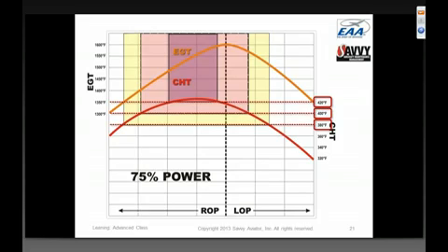it, sort of a caution zone that we would prefer to stay out of, and a purple box in the middle, which is an area that's highly abusive. And so, for the sake of argument, for a typical legacy aircraft at normal outside air temperatures, we'll say that the preferred limit is 380, the absolute limit is 400, and if you get to 420, that's a very, very abusive situation. Again, just a slight modification to the red box concept, just to emphasize the fact that